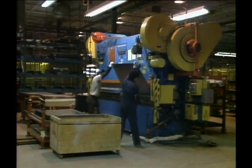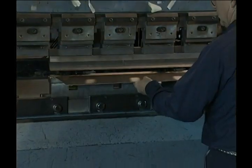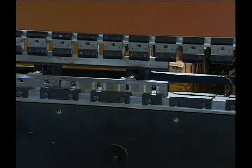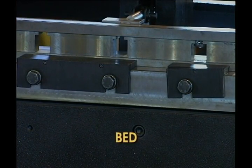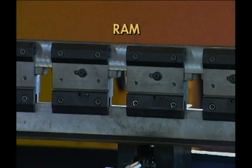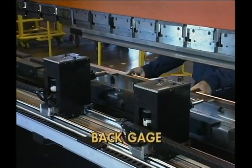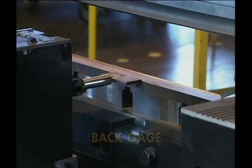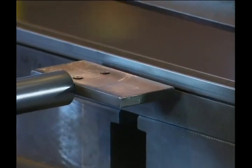Press brakes can generally be divided into two categories, mechanical or hydraulic, depending on the type of ram drive that is used. The principal components of a press brake are the bed, which is the lower portion of the machine that supports the lower or female die, the ram, which holds the upper die or punch, and the back gauge, which can be either a bar or fingers at the back of the press brake that position the workpiece so that the bend is made at the desired point.